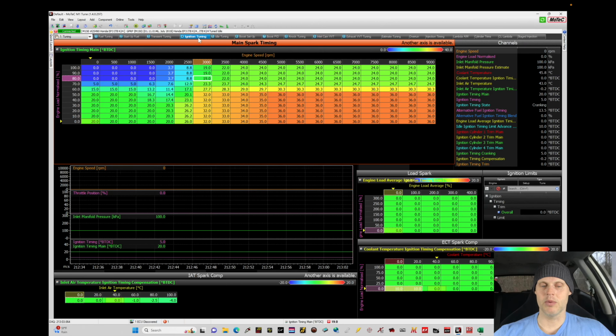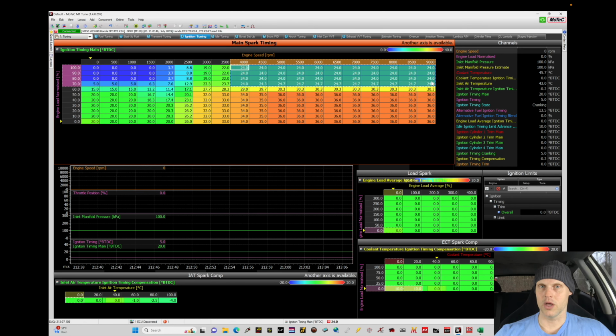Now the other thing to keep in mind here is ignition tuning. We know we ended up with 24 degrees of timing on low cam. We're going to be able to run at least this much timing on high cam, possibly another degree or two more when we're on VTEC activation. Cylinder pressure changes a little bit, and we have a little bit better breathing. As a result, we can usually get a little bit more aggressive with our spark advance without running into knock. We'll have to experiment with this, but these values that we found for low cam will work perfectly fine and be completely safe for high cam engagement.